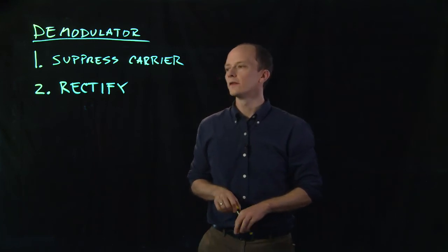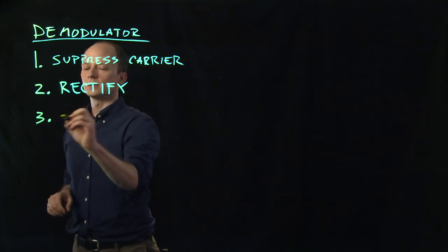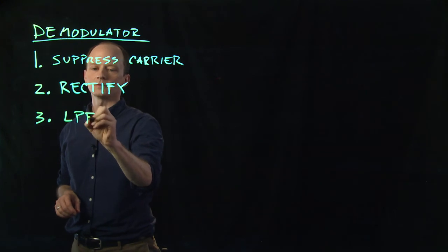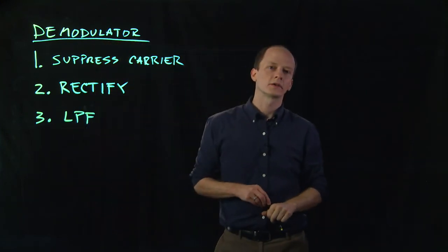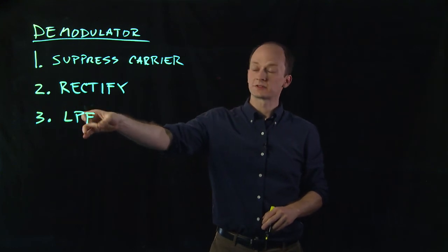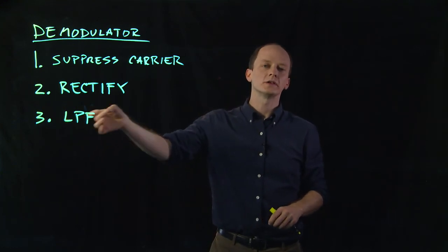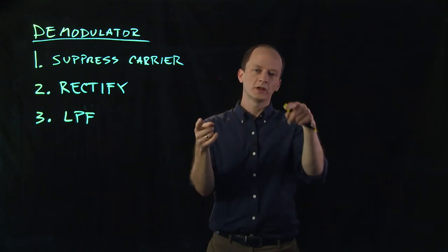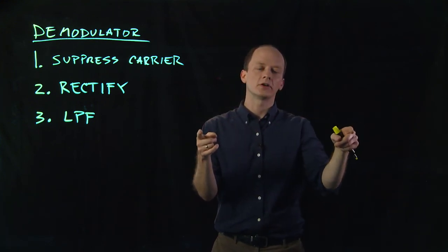Okay? And then finally, you're going to need something to low-pass filter this rectified signal. The idea is that this low-pass filtered signal is going to give us the information about the actual signal, the modulation of the amplitude of that carrier frequency.